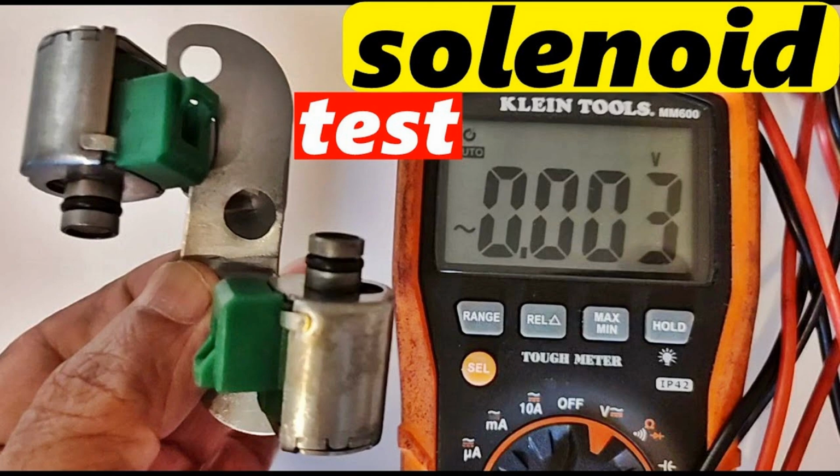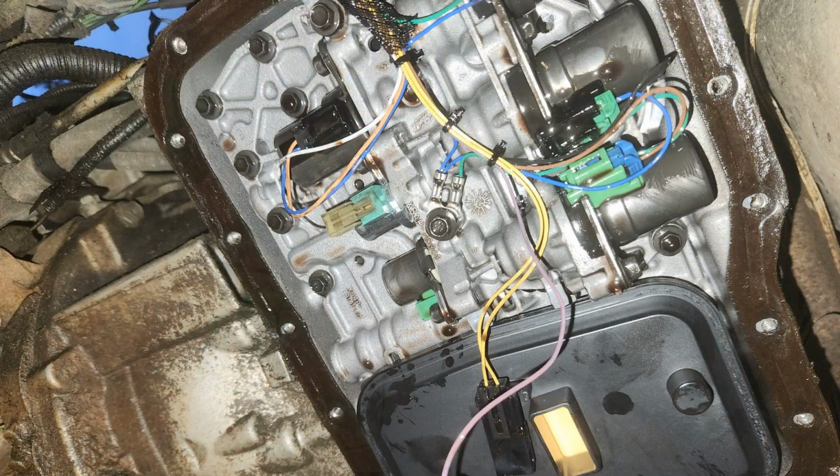If your automatic transmission has a collapsible solenoid design, the winding itself must be replaced. The part can be washed in gasoline or other cleaner, then dried and reassembled. If the serviceability test of the reconditioned part is successful, it is returned back to the solenoid unit. It is not difficult to completely replace the solenoid when the test has shown a complete failure.